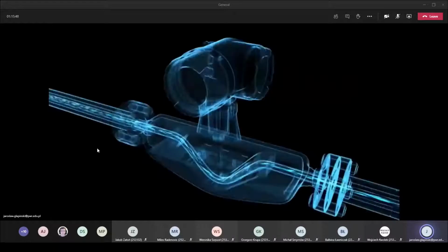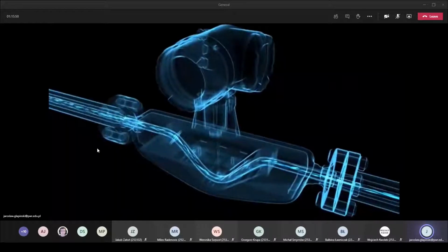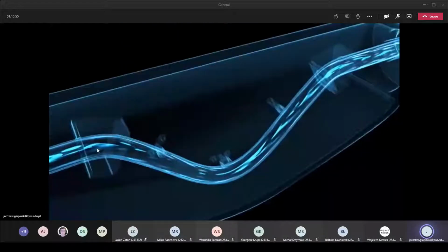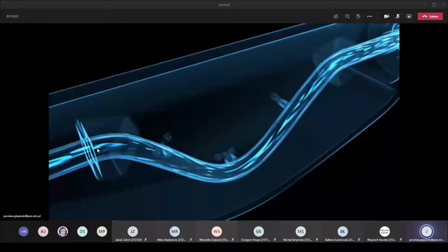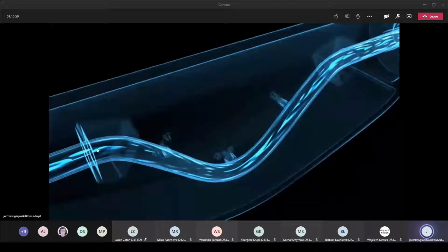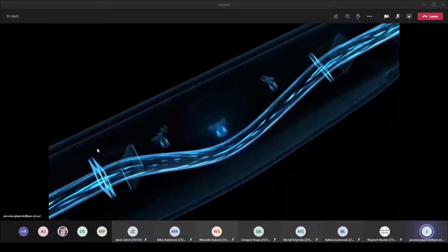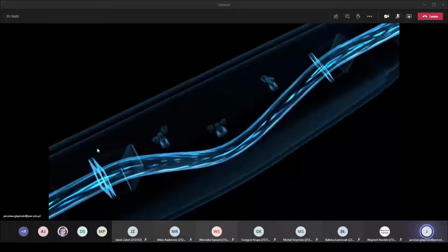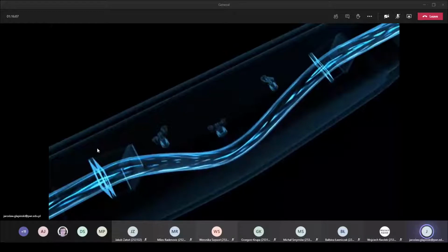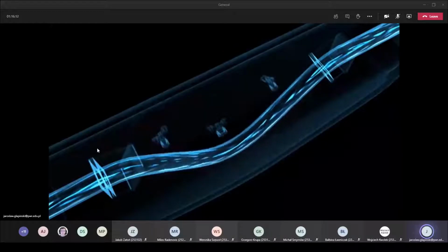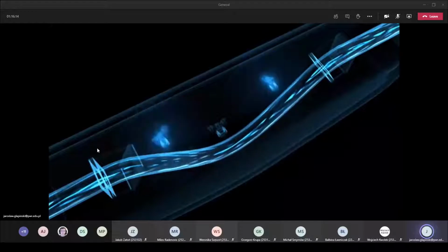Let's take a closer look at how this measurement method works. A tube is located inside each Coriolis flow meter. An exciter causes this tube to oscillate constantly, here in an exaggerated example. If there is no flow, the measuring tube oscillates uniformly. Sensors are located at the inlet and outlet and register this basic oscillation precisely.